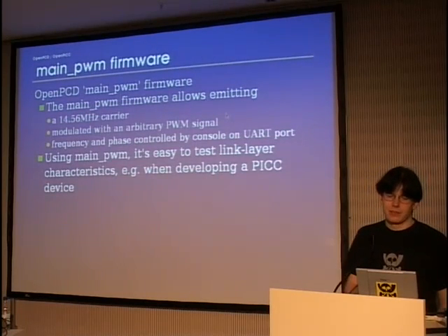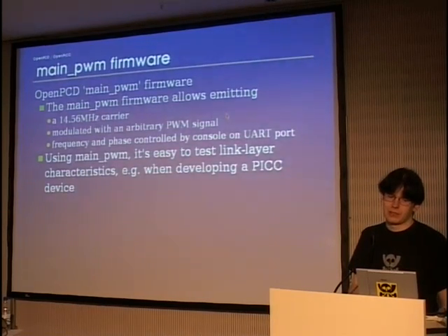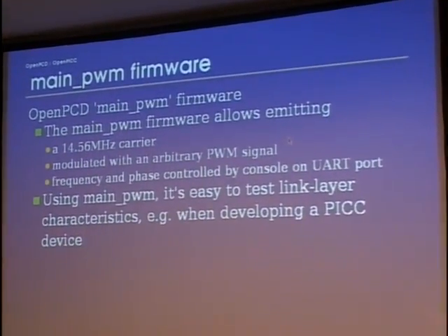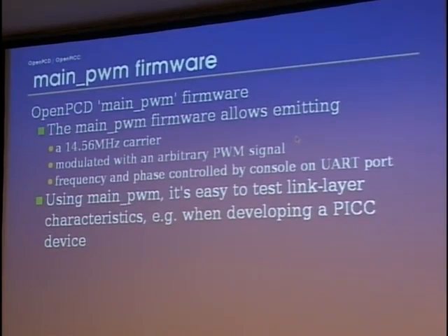There's firmware images for debugging, such as the main PWM, which you can use to transfer arbitrary pulse width modulated, it's obviously on a 13.56 megahertz carrier. It's an off by 1 error. Even in non-integral numbers. Anyway, so you can create PWM signals, which is basically arbitrary waveforms, arbitrary phase, arbitrary frequency, pulse pause ratio, whatnot.